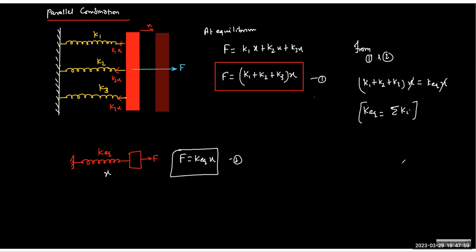If you add n identical springs in parallel, the ability to pull, or you can say the spring constant, will grow by n times. Okay. Because parallel means they cannot have different deformation. They can have only equal deformation.